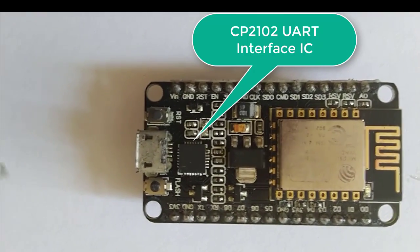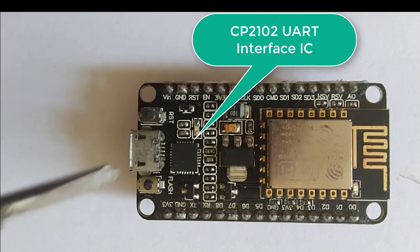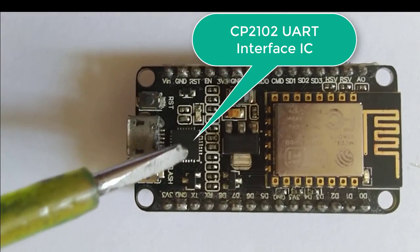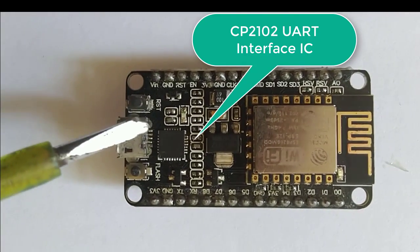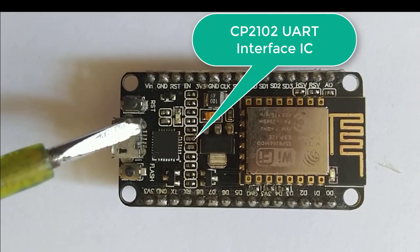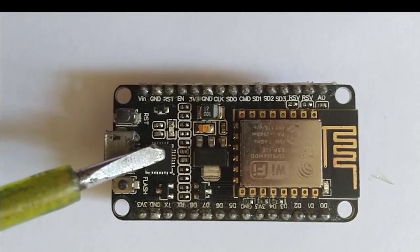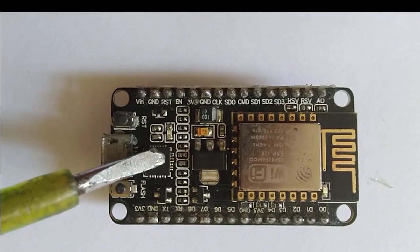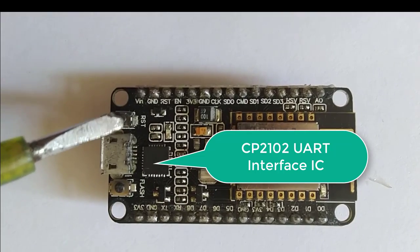And this NodeMCU development board has Arduino like analog and digital pins on its board, and it also supports serial communication protocols like UART, SPI, I2C, etc. Using such serial protocols, we can connect it with serial devices like I2C enabled LCD displays, HMC, MPU, RTC chips, GPS modules, touchscreen displays, etc.